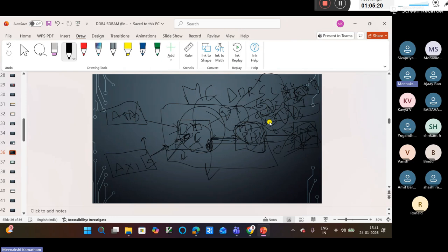In my TB architecture, I have two agents, the APB agent and the AXI agent. The APB agent is mainly to configure the registers of the controller block and PHY block, and AXI is mainly used to initiate the traffic. Then the controller does the conversion of logical data into physical data, plus arbitration and command scheduling. All these things are done by the controller block, including timing calculation and timing correction.